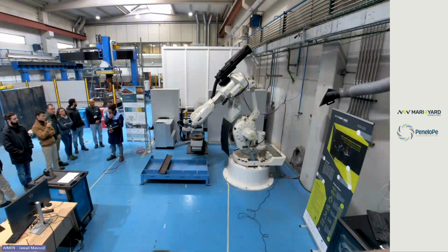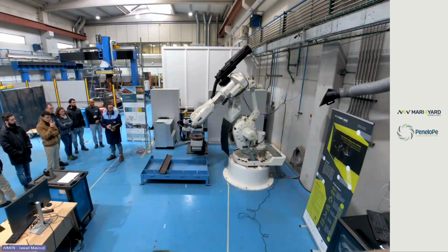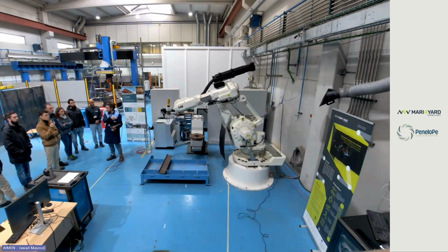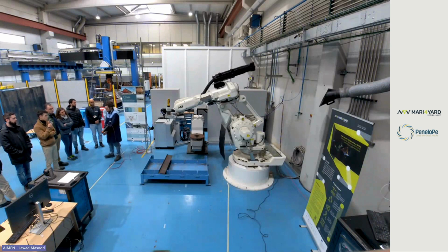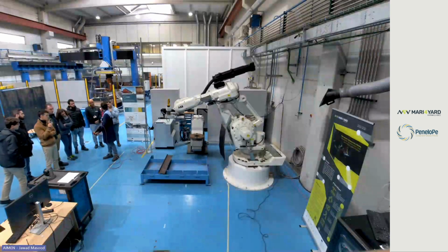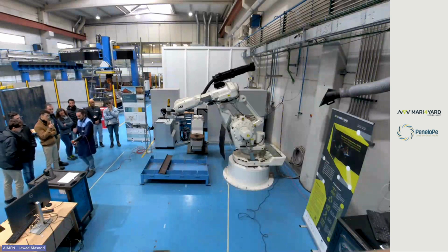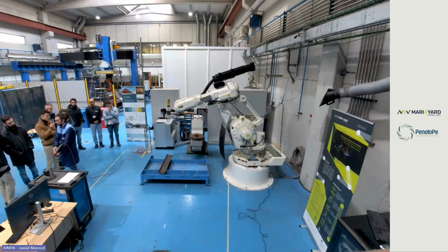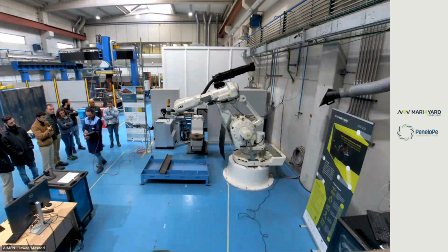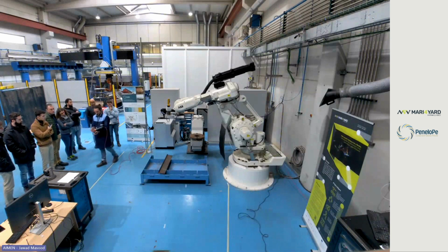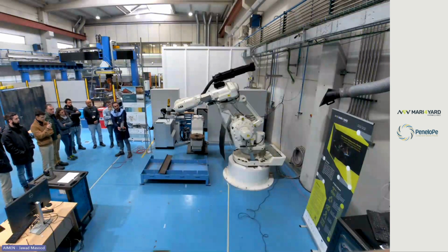Okay. First, I'm going to execute the first movement, move G P home, and the robot moves from the point it is to the programmed position, right? Now, if I push the play button to execute the complete sequence of the main routine, calling the square routine, etc., the robot is going to perform the complete sequence, just one cycle. Let's see. I'm going to push play.